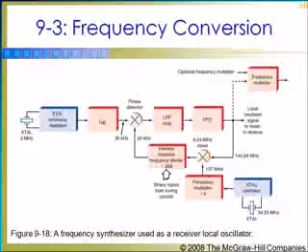One approach to this problem is to use a prescaler to reduce the VFO frequency before it is applied to the variable frequency divider. Another is to reduce the VFO output frequency to a lower value within the range of the dividers by down-converting it with a mixer, as illustrated in the figure.